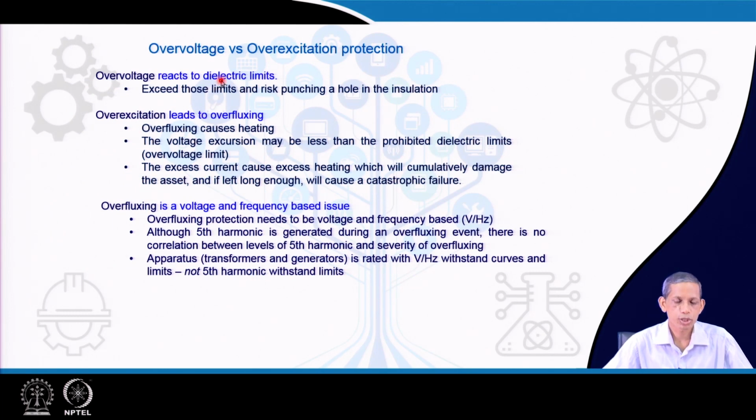So, now to distinguish over voltage versus over excitation protection, you need not confuse them from this perspective. We are talking about differential relay protection. Differential relay protection should operate only when an internal fault happens in the transformer, and in that case neither the inrush situation nor the corresponding over excitation situation should allow the differential relay to operate.